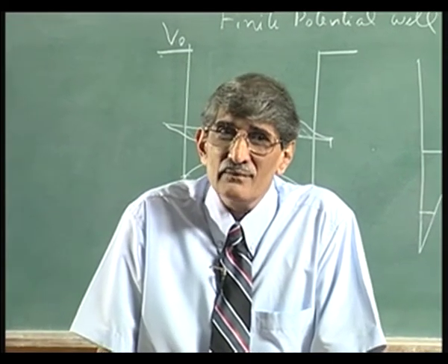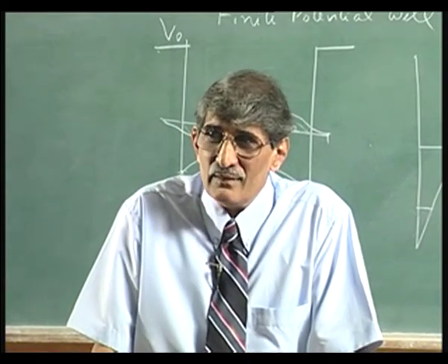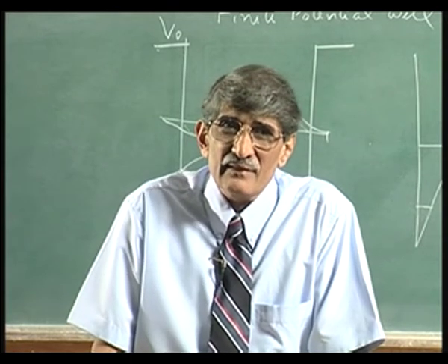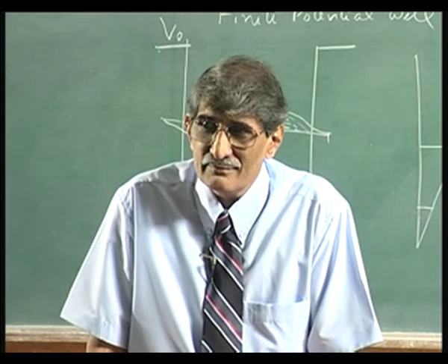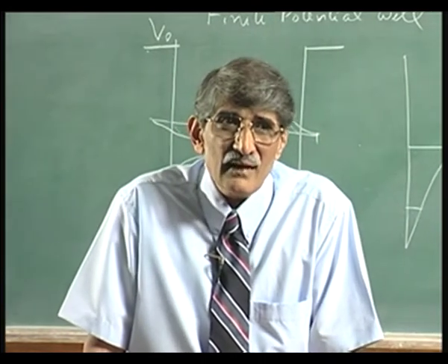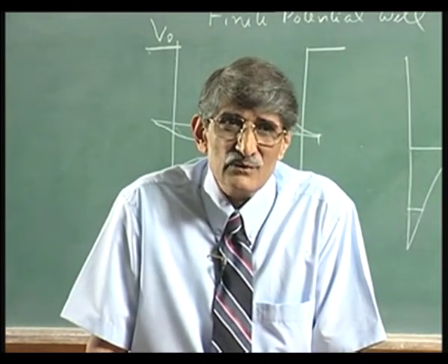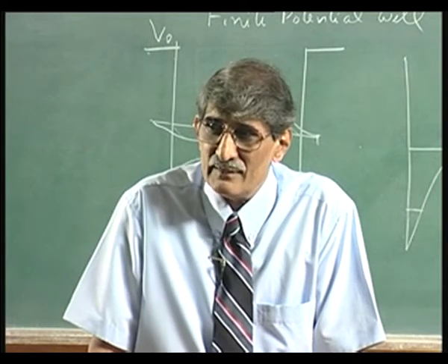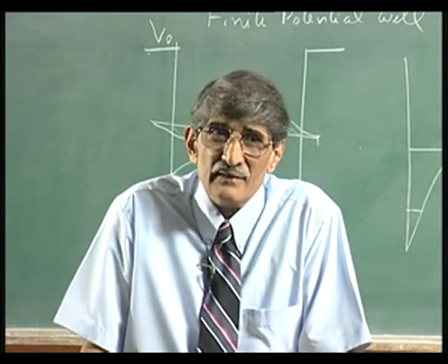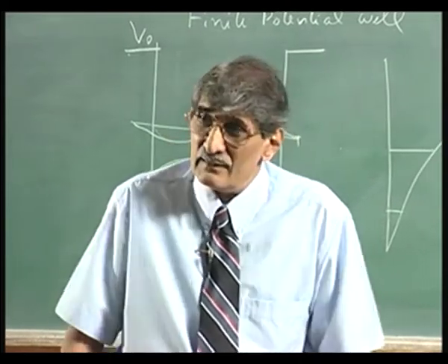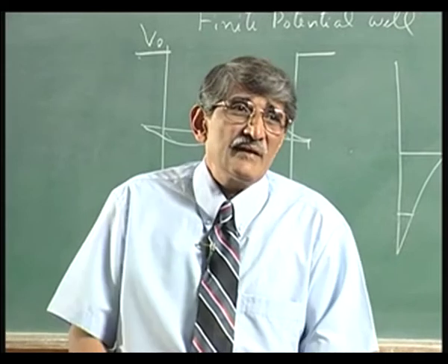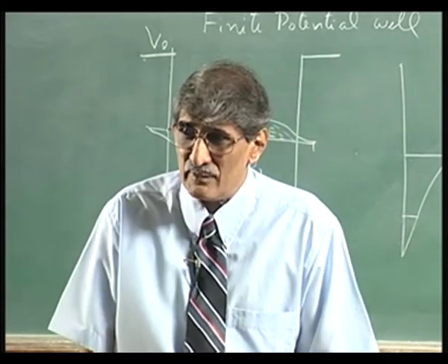If you recall, the higher the band gap material, particularly N type, the higher is the barrier height, 2/3 of Eg, and its interface density is high. Higher the band gap, higher the barrier height, less chance of making a good ohmic contact.